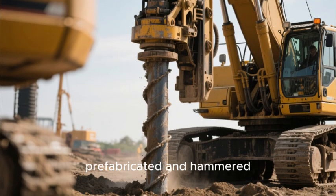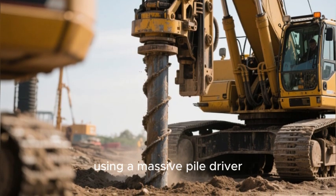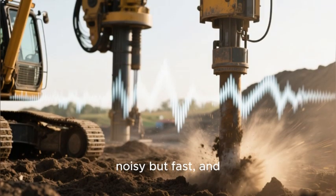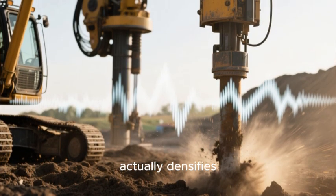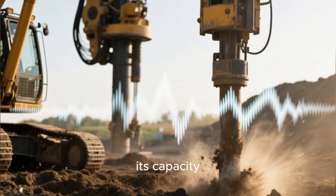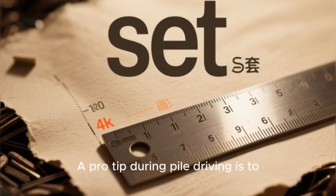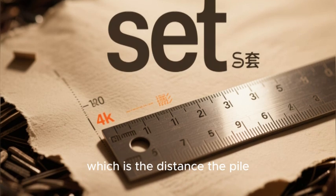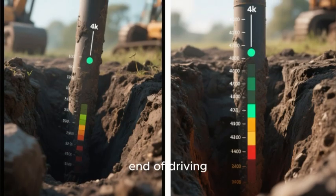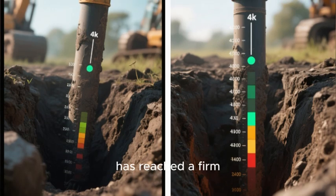Driven piles are prefabricated and hammered into the ground using a massive pile driver. This process is noisy but fast, and the act of driving actually densifies the soil around the pile, increasing its capacity. A pro tip during pile driving is to monitor the set, which is the distance the pile penetrates with each hammer blow. A high set at the end of driving indicates the pile has reached a firm layer.